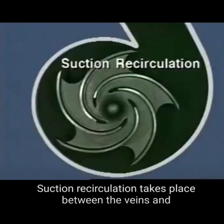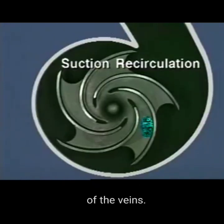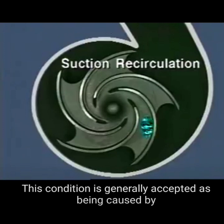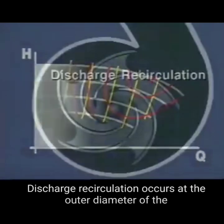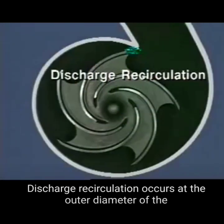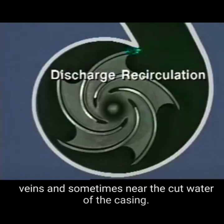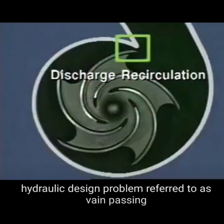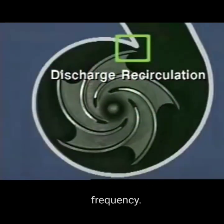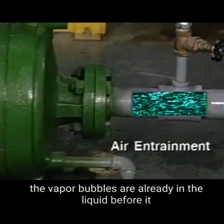Suction recirculation takes place between the vanes and causes pitting damage along the trailing or concave side of the vanes. This condition is generally accepted as being caused by operating the pump at very low flow rates. Discharge recirculation occurs at the outer diameter of the impeller and results in pitting damage at the tip of the vanes and sometimes near the cutwater of the casing. This can also be caused by a low flow condition or by a hydraulic design problem referred to as vane passing frequency.